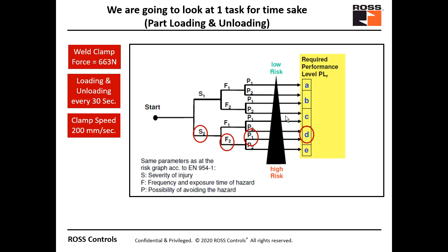And those of you who have robots probably know that when it's in program mode or in teach mode, it is limited to 250 millimeters per second, or 10 inches per second. It is in a slow mode, and that's where the safe speed reference comes from. In many cases, it is from the robot standard.